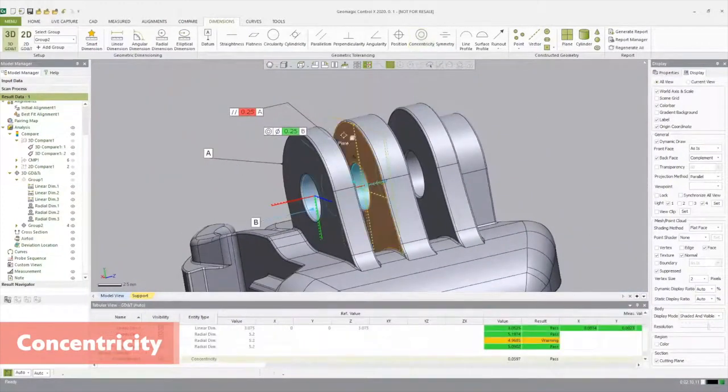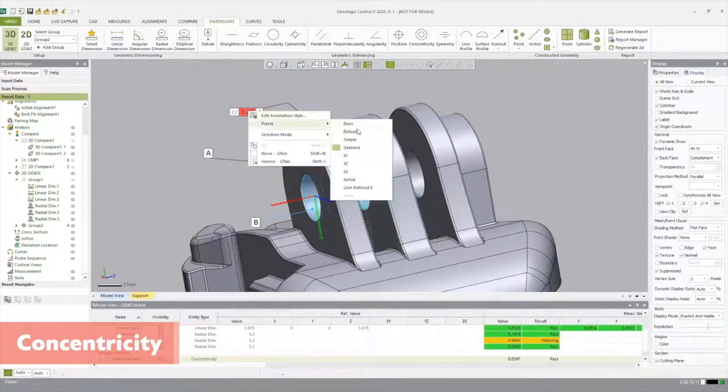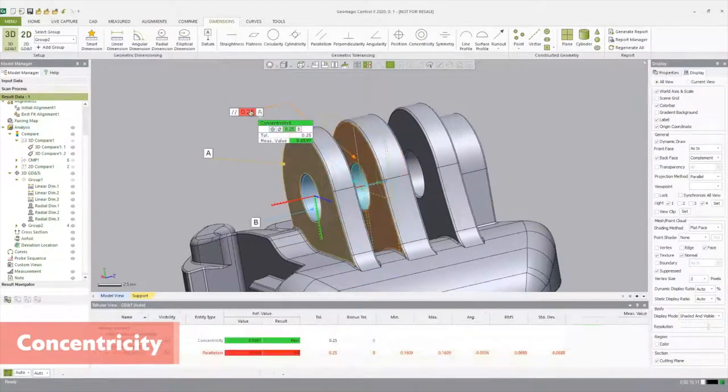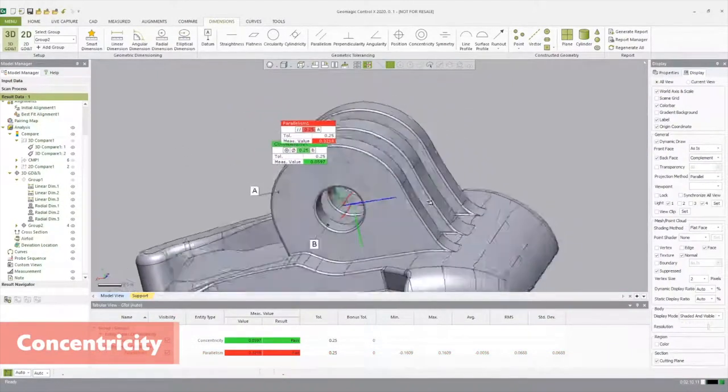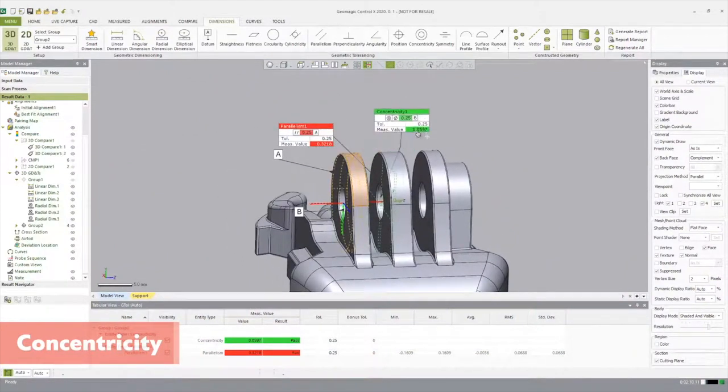And once again, for reporting purposes, orient the part in a way that best depicts critical information. Highlight 3D GD&T in Group 2 in the Model Manager, and in the Result Navigator hit the Reassign Viewpoint, and this will now be generated in the final report.